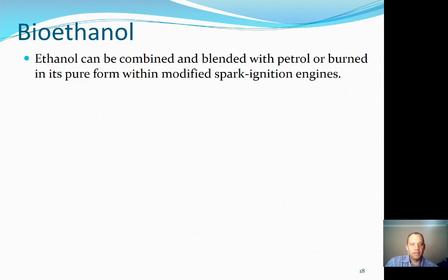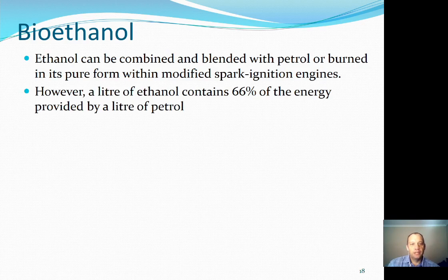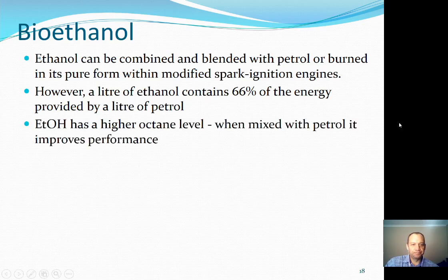So we start off with bioethanol, which we've mentioned previously can be combined and blended with petrol or even burned in its pure form within modified spark ignition engines. Those are the flex fuel vehicles that we mentioned earlier. However, a liter of ethanol contains only about 2/3 of the amount of energy that you get in a liter of petrol, and so if you're filling up with ethanol alone, that means you'll be filling up more regularly.